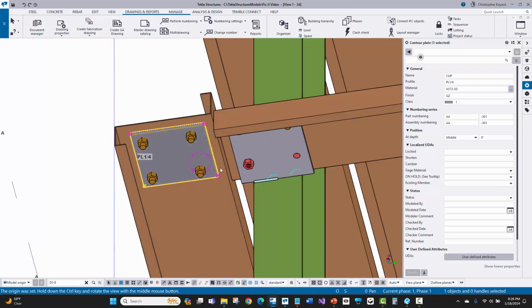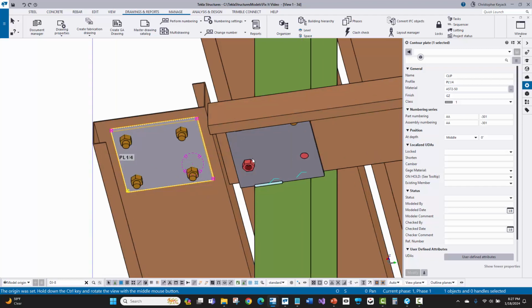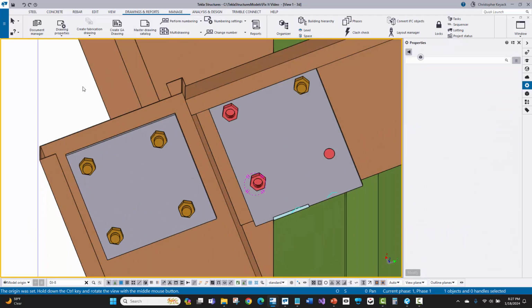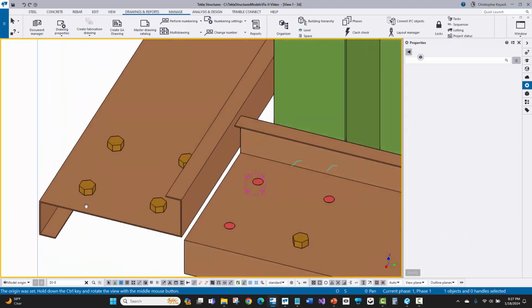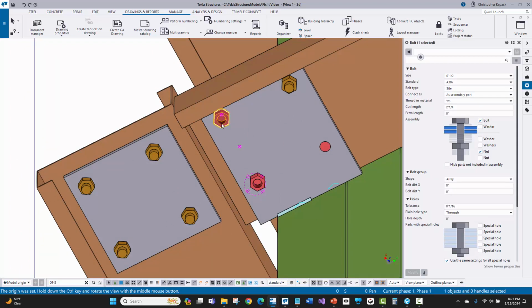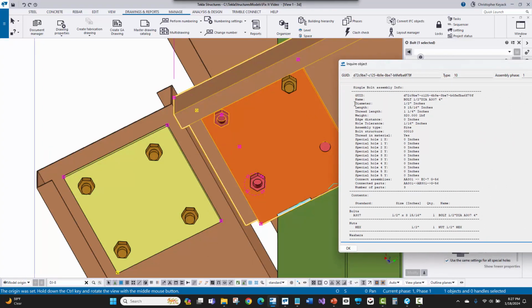Or SlideRule will put it in, and instead of it extending across here where it's supposed to be to bolt that up, it's put it in the wrong spot. So there's a couple things that probably need to be fixed. I'm mainly going to focus on just this bolt problem though. If you look in here, you can see that there's these bolts and they turn a red color or a pink color. What's going on there is that a bolt is trying to be put in there, but it's not working properly. So let's go ahead and inquire on this and we'll see exactly what's happening.